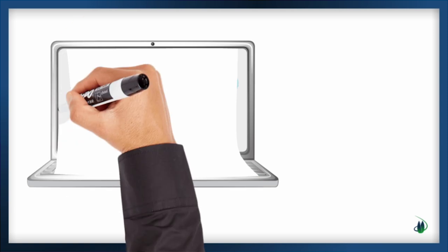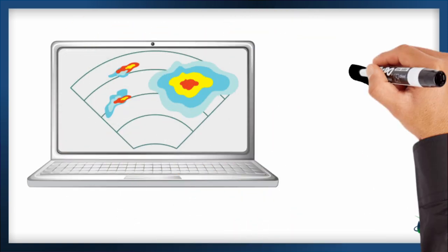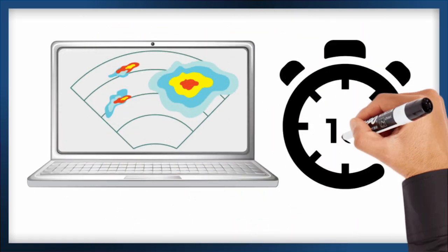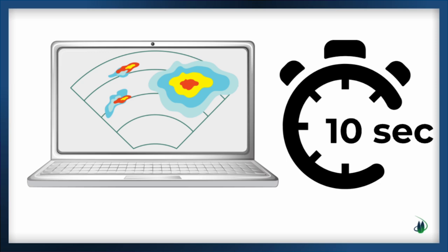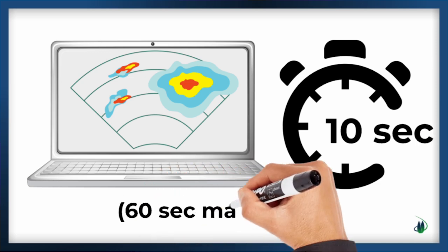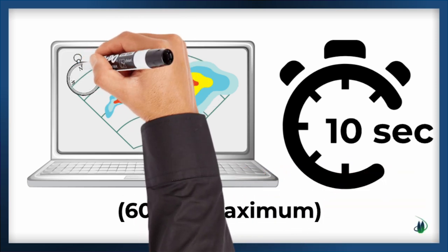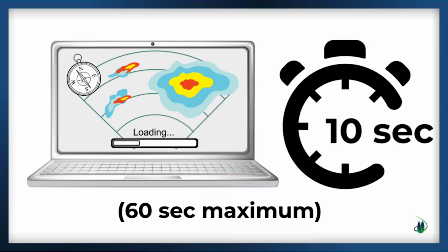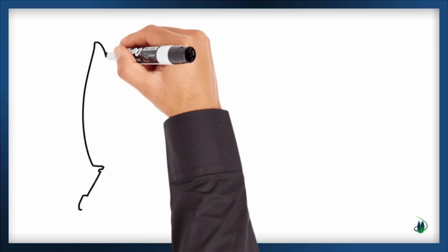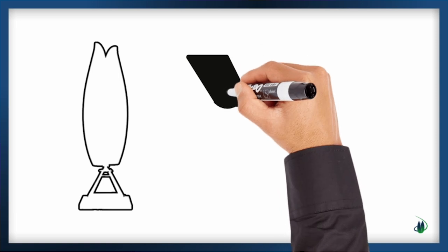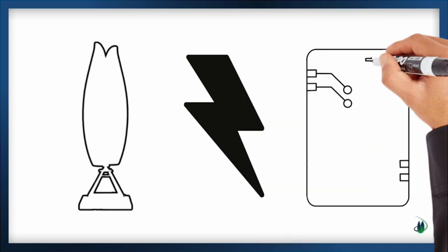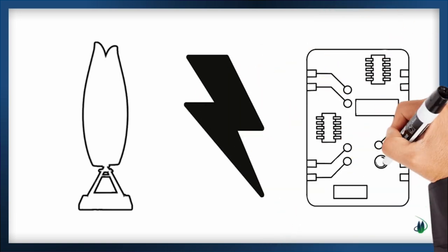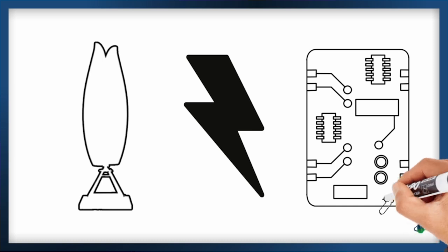If you decide to measure your wind information, you should choose a weather station that enables you to record measurements in ideally 10 but up to 60-second intervals, determine wind direction, and download a time-stamped spreadsheet of these values. The average wind speed helps set expectations for the project's performance. If it's exceptionally high or low, we may need to adjust or replace the turbine's electronics to match.